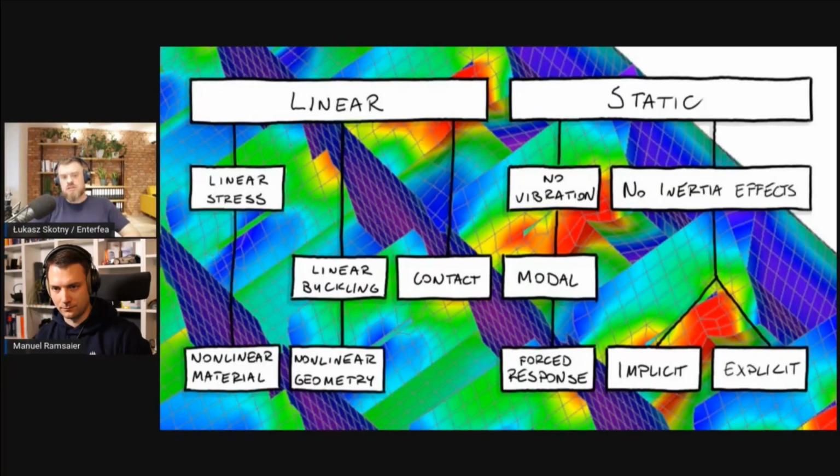That's doable, especially since the advanced nonlinear solver in FEMAP that I'm using would use time either way. Whether you do static analysis or transient analysis, the time will be there in your model. It will just take or not take inertia effects into account on the click. So even if I say I want nonlinear static, it would still ask me to define time just to iterate the load through, like linear.